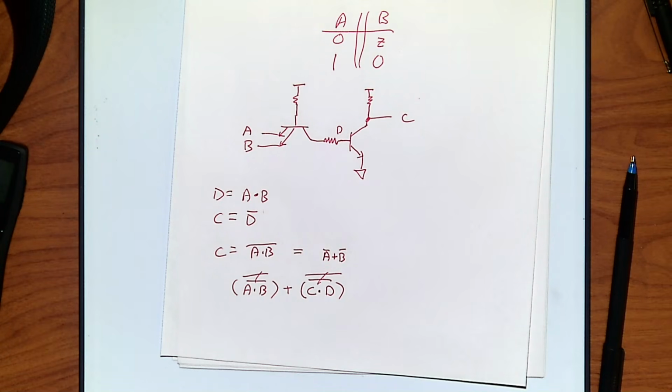Why? Because it's slightly faster because we're mainly using electrons. Where when you do PNPs, you're mainly using holes, and holes are a little bit slower than electrons because it's like an electron with some extra steps. So there's a slight advantage in NPNs. Now, there are some cases where PNPs, and we'll take a look at some, right? There are some cases where PNPs actually become quite useful, right? And it's nice to know that.